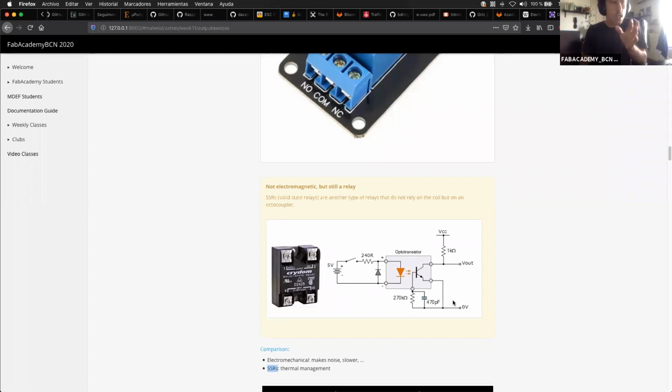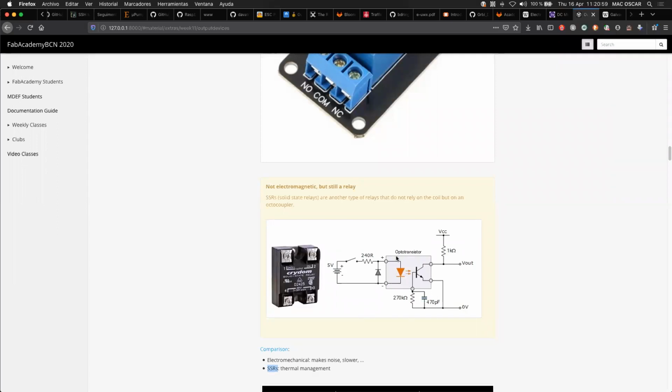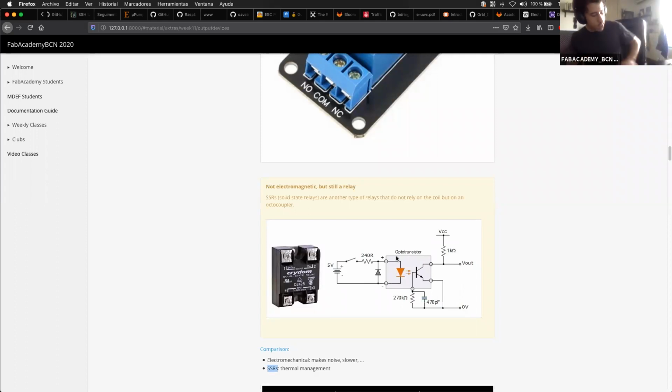Does that make sense? Yeah, so here, as I understand, the Arduino controls the relay to let higher voltage and current flow. Exactly. And it can be totally different types. For example, you can control a relay that handles not only DC current, but also AC at 230 volts, for example. And you can turn on and off a lamp, the normal one that is plugged into the socket in your wall, by putting a relay in the middle that you control with an Arduino or a microcontroller.